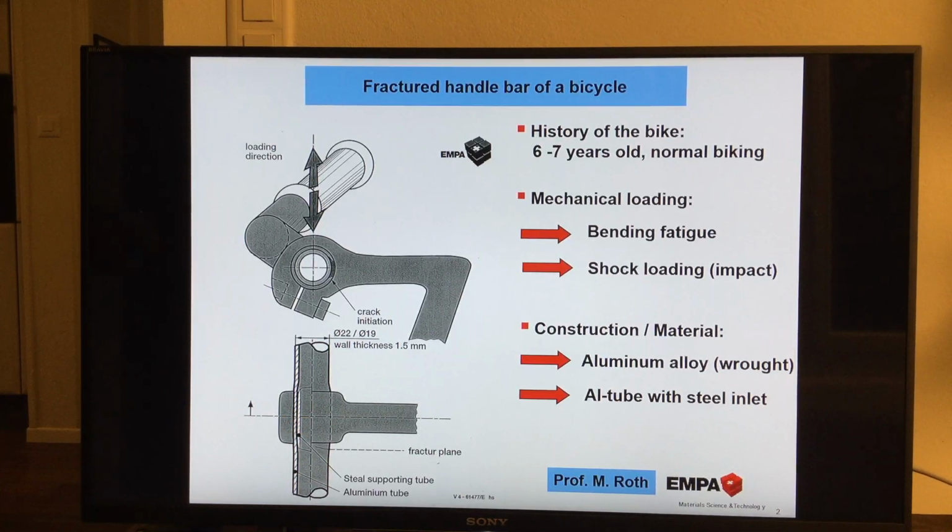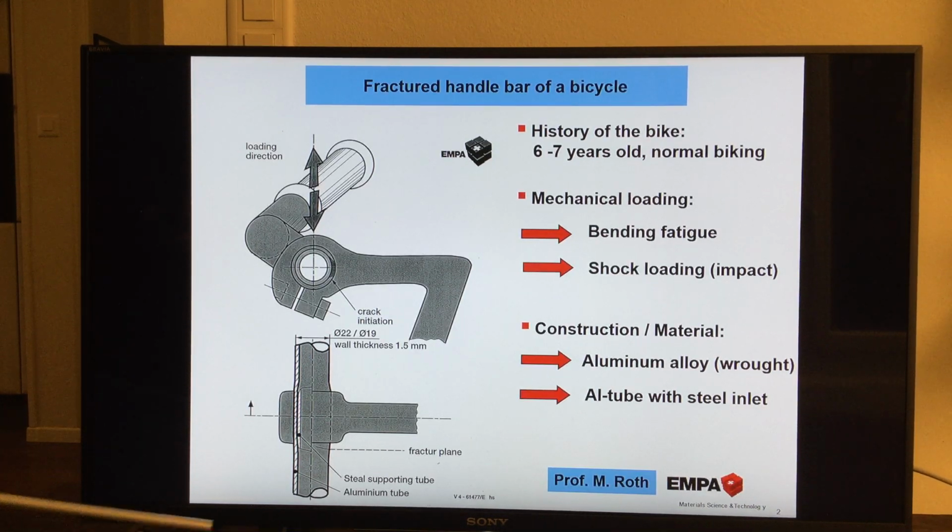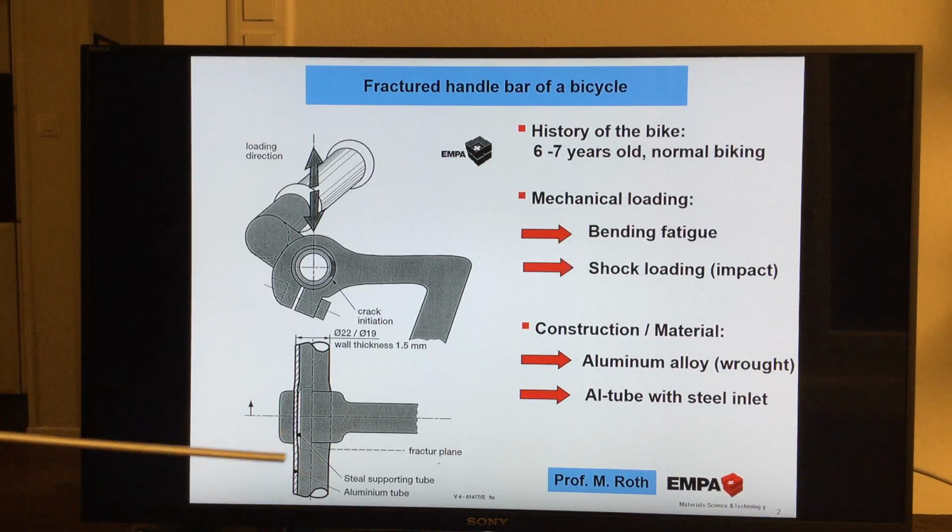Two different materials. What does it mean? It's like a battery. And when we have a battery, then there is electric current flowing, and when we additionally assume that there is also humidity, trapped here all the time, that means that there is corrosion taking place.